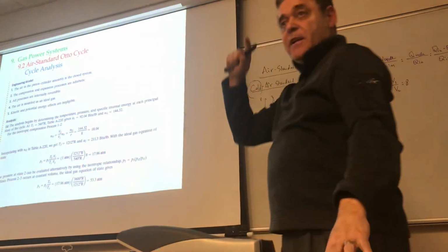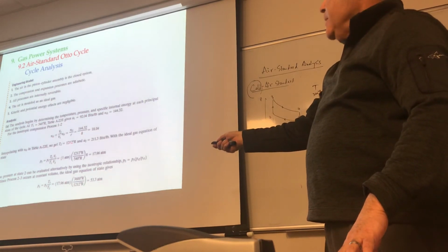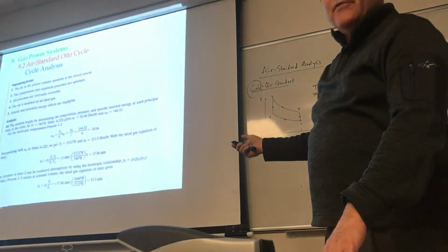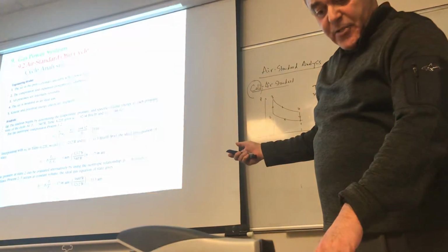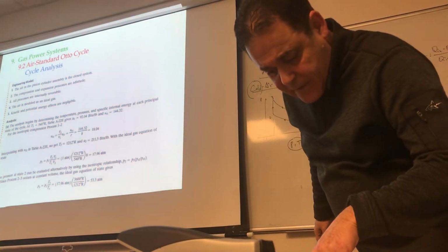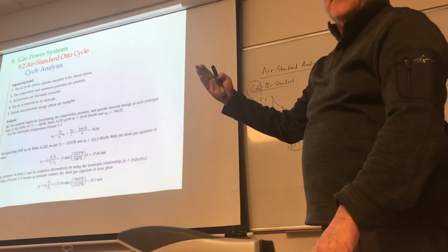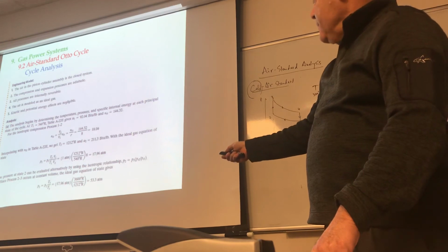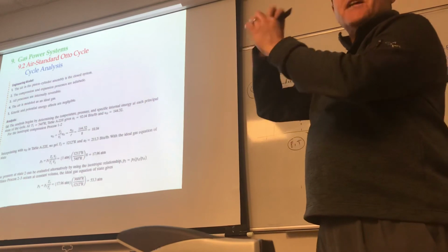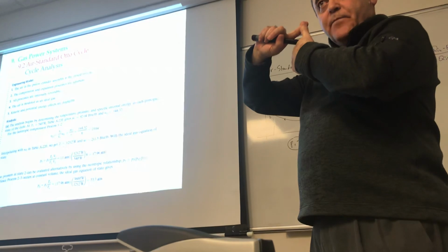So you calculate VR2 over VR1, which is the same thing as V2 over V1. Once you find this, we find what that next state is, and by the same token, what is my value of U2 going to be? Well, it's going to be between 208.05 and 216.53. Which one? It's going to be interpolated likewise, right? And you should be getting something like 211.3.